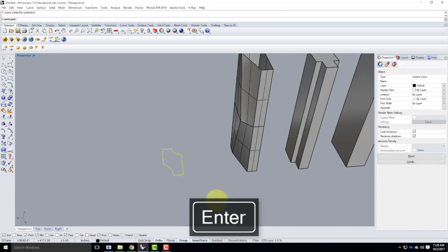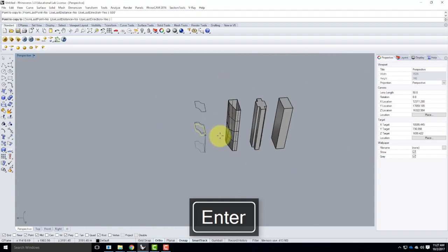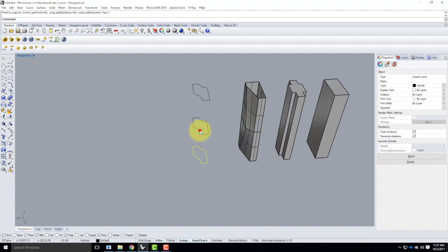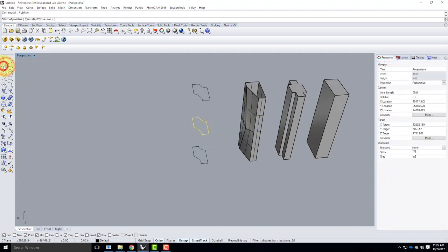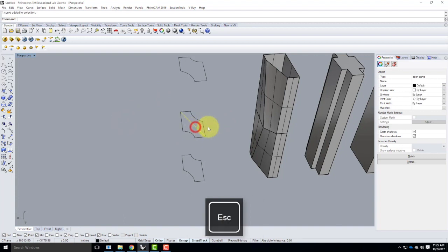And let me go ahead and move or copy V for vertical. And we'll go up 300 feet and then 600 feet. Now you could, of course, I'm doing it in 300. You could do it every 100 and it could change every 100 feet. You could do it at 150, whatever divisions work. Let's take this particular piece and I'm going to rotate this one around the center. So let me create a temporary line there. And I'll take this piece, rotate. It's a regular rotate, not a 3D. And we're going to flip it so that it's like that.